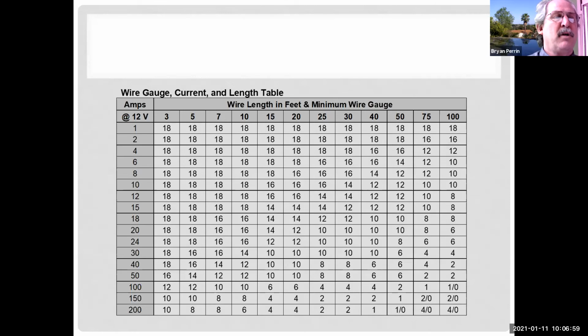I know we got a lot of stuff going on. I'm going to turn on module 3, which is batteries and starting and charging. So we're going to get that turned on, and we're going to start getting into batteries tomorrow. And tomorrow, I'm going to break it to you that our 12-volt batteries are not 12 volts. But I use 12 volts because the math is easy. So we'll actually get into and find out that if your 12-volt battery only has 12 volts, it's actually dead. And talk different ways about how to test the battery. So on that note, I think we're good for the day.